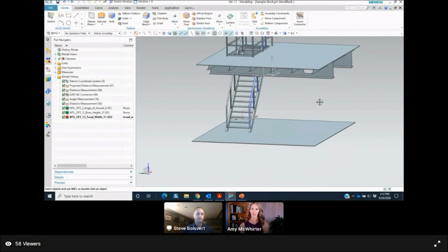Okay, good. And then do you always have to manually link a measurement to a parameter? No, you do not always have to manually link a measurement to a parameter. Actually, in this case, the riser height was an example where that value already existed. So it either existed within a dimension or the designer added that parameter into the model to control something. And just by the nature of how we bind parameters together, because their names were exactly the same, we're able to take that value and rule process against it and then send that result back to the model.